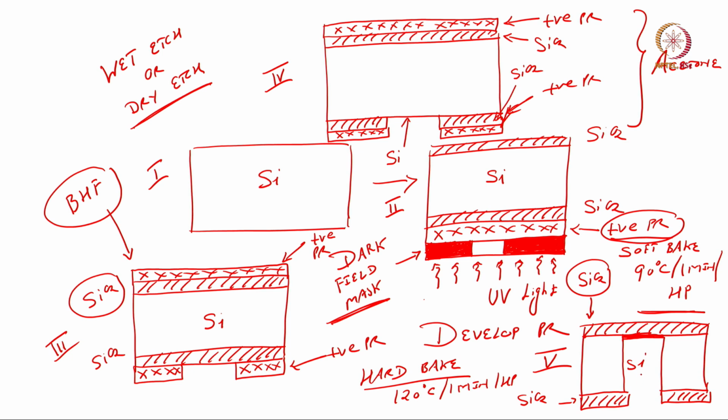If we used the wet etching process instead of dry etching, what kind of wafer would we have? We will have a wafer which will look a little bit like this. Now, I am not etching all the way, let us say here silicon dioxide is there. Here what you see is there is an angle that is created which is 54.7 degree. Here also we have created a diaphragm, that means we have etched silicon but using chemicals.